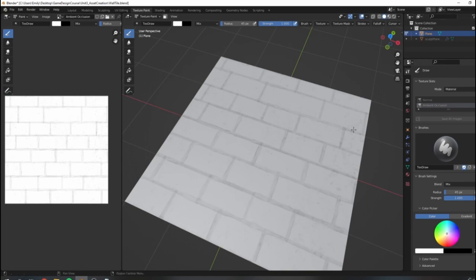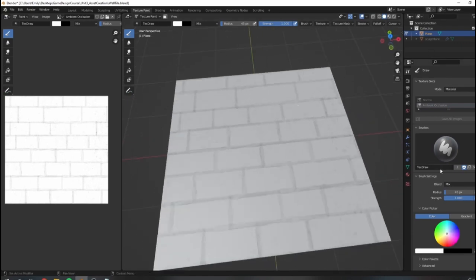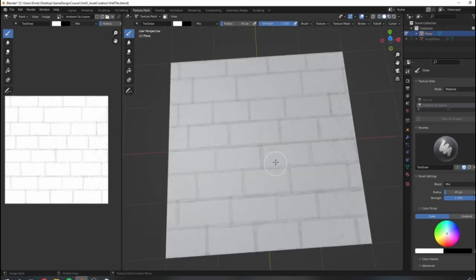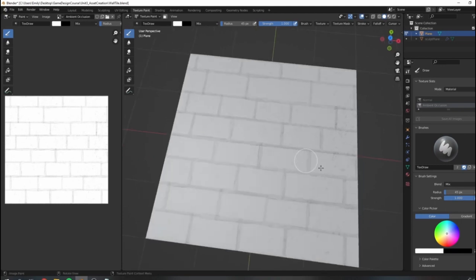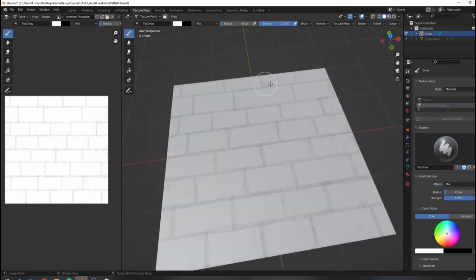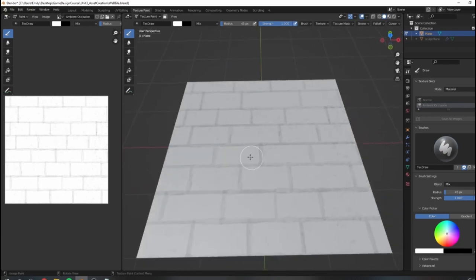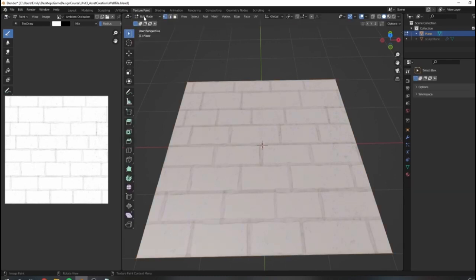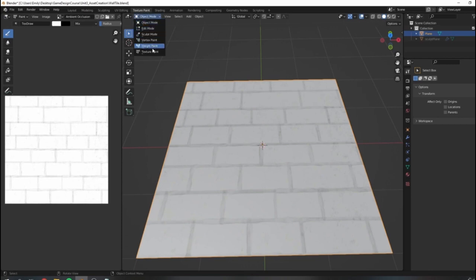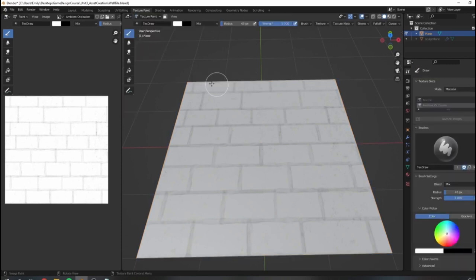in our properties panel. So what I need to do to start painting on this is to add a base color texture to paint into. And while you certainly can do it the way that we did for baking, for the purposes of texture painting, there's a much faster way. So within the texture paint tab and within texture paint mode, which, if you have accidentally gone into object or edit mode, you can quickly find again by selecting it in the drop-down menu.